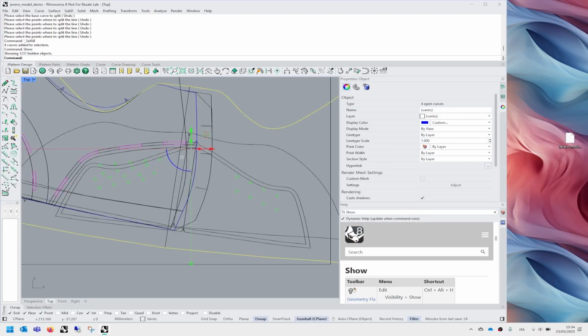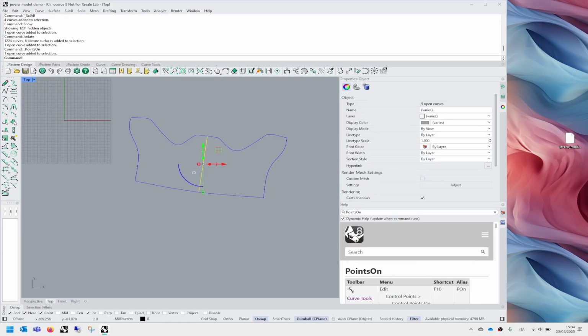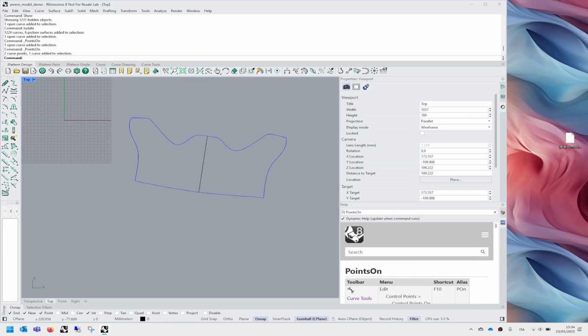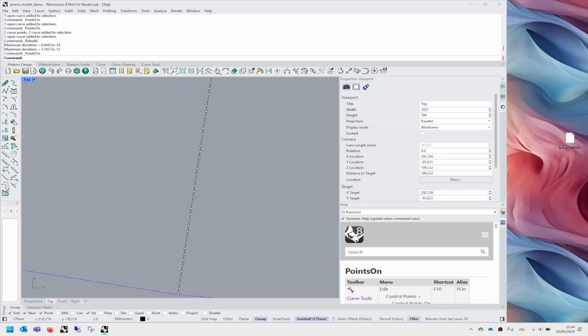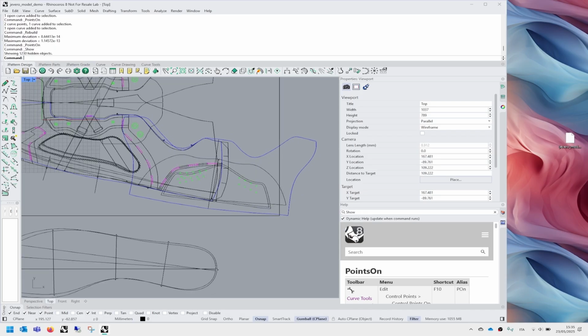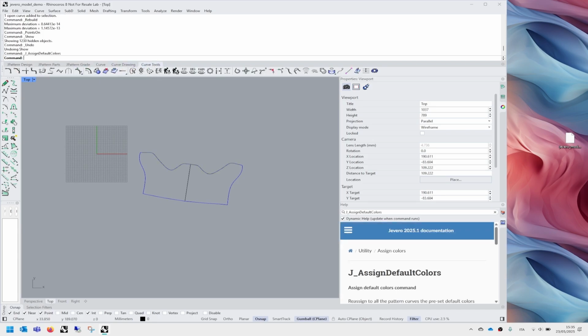You can also get some axis here. Sometimes this curve is fine, it's just 2 points, but sometimes what you get is stuff like this, which is not ideal for creating axes for mirroring. And there is a tool that's called simplify lines and arcs.